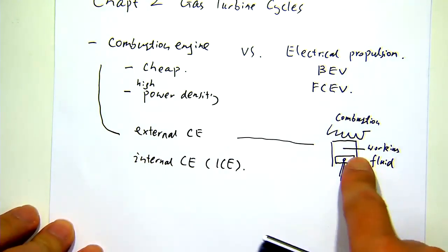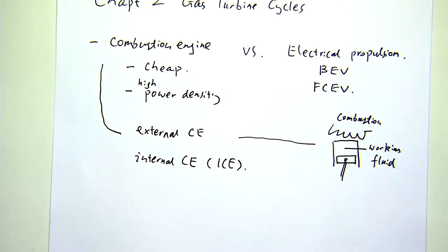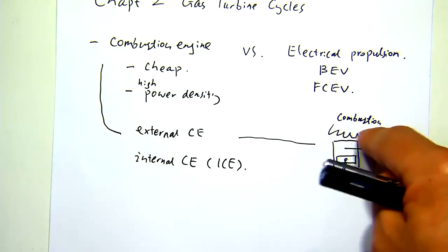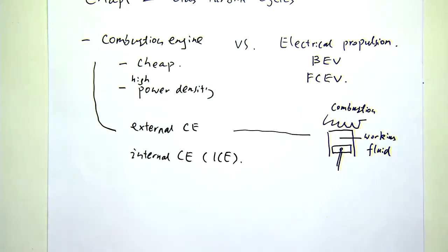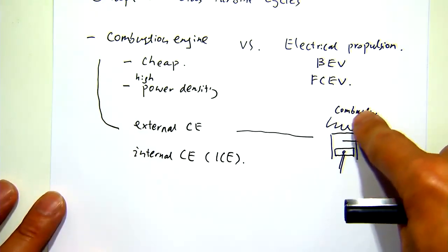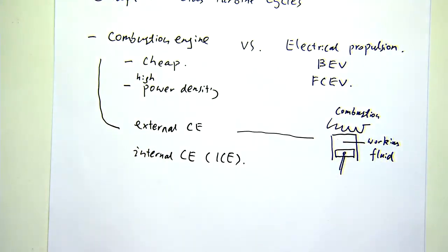This process is not very fast, because later on when we learn heat transfer, this is basically a gas transferring heat to another gas. So in terms of heat transfer rate, it is inherently slow. The two gases are separated by a wall, so you have to rely on convection to the wall, wall conduction, then convection to the gas inside. So this process is limited by heat transfer and is inherently slow. But that's actually the first type of combustion engine that has been invented.